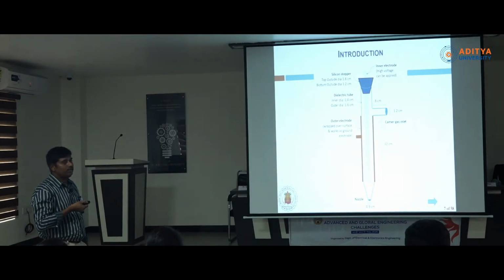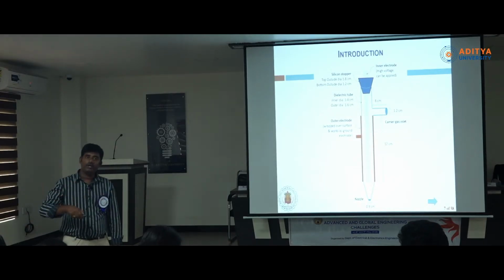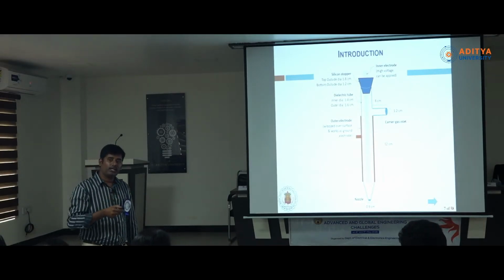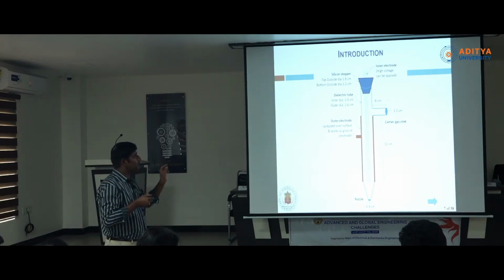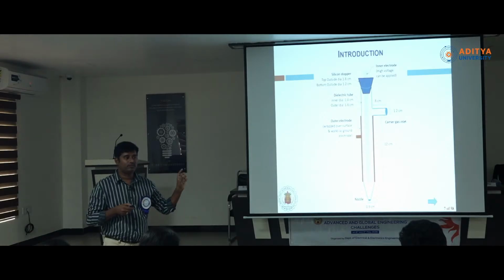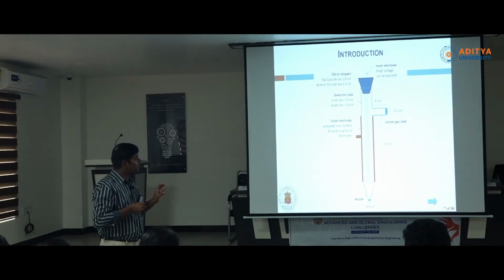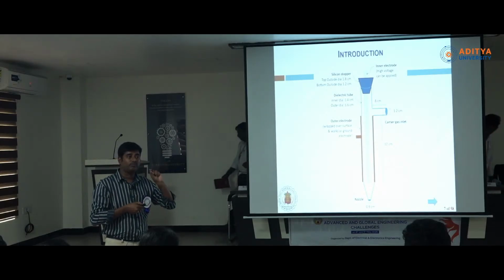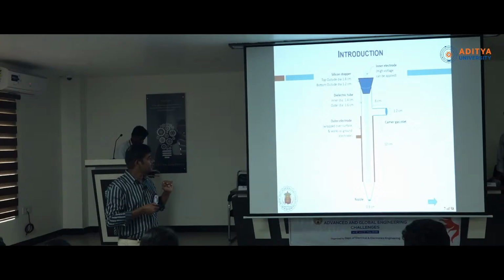The electric field intensity inside the tube will be very high when we apply high voltage. You can see on the surface of this tube we have a ground electrode also. Aluminum foil we need to wrap around the tube, and it needs to be grounded. The medium between this high voltage electrode and ground electrode is nothing but the glass tube wall. That wall itself will act as a dielectric barrier between the high voltage and ground electrodes,